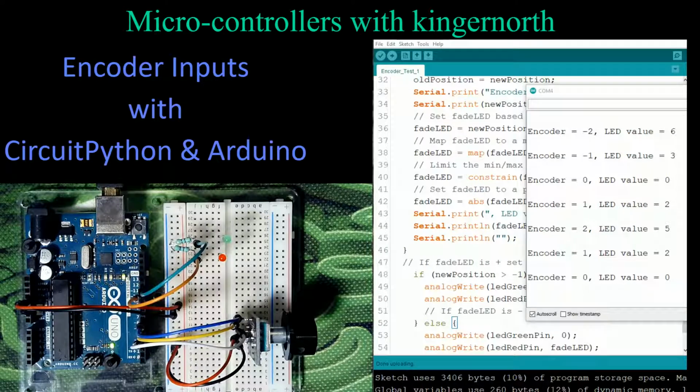If you add a transistor and the actual motor circuit on the outside to vary the voltage instead of just varying a light, you could use it to vary the voltage to a train track. You can now run a train. Why is this handy? Because you could have it set up on your model train layout. Maybe you've got a conveyor that is traveling to haul ore on your mill. You could fine-tune the speed of it, and you can control it from here, make an adjustment with it, and then later on, if you decide it's too slow or too fast, you just turn your encoder a bit and change it. If you want it to run the other direction, you can do that too. So now you have some manipulation that you can do, and you can start controlling things with small electronics like this. So it actually gives you some capabilities.